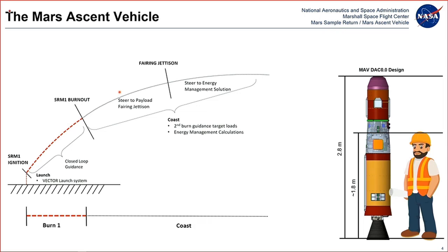So one inertial pointing direction, solid rocket motor, so you don't have the ability to cut off at all. So it's the objective of energy management to determine when the right time is and what the right orientation is to burn, so we can get successfully in orbit and minimize our dispersions. But anyway, so that starts its computations up, and then after that, we are holding that one inertial attitude.